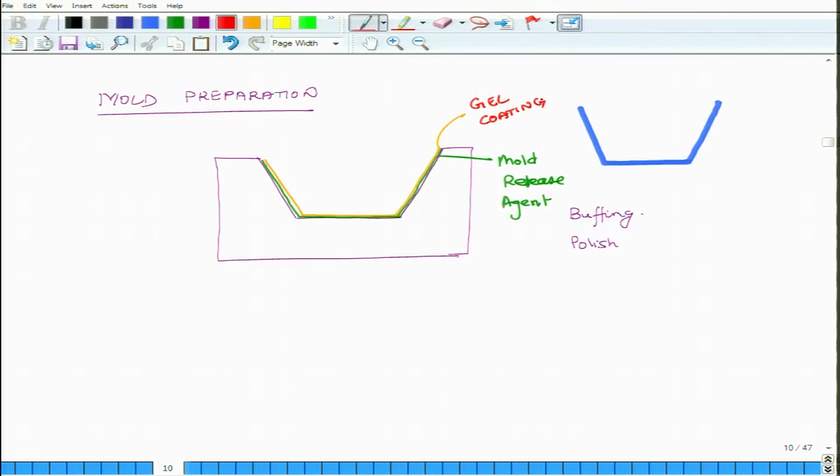And this makes sure that the overall surface has no roughness and it is pretty smooth. So, this is how you broadly do the preparation of the mold, and then you start putting fibers. Now, in context of fibers, I wanted to say two things. You can put fibers in two ways. First way is, so it depends on the requirement. So, there could be a reason why you are interested putting some randomly oriented fibers.